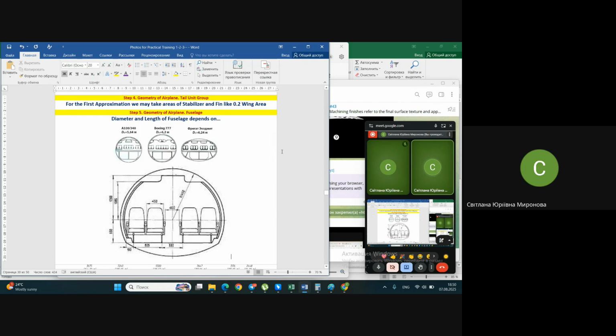Knowing the absolute value of payload and understanding the relative mass portion of payload inside this airplane, we are able to calculate the takeoff mass of the whole airplane. Next, understanding the balance of forces acting on the airplane, we insist that the weight of the airplane equals the lift, and lift determines the wing area. After this, we have calculated the wing area.